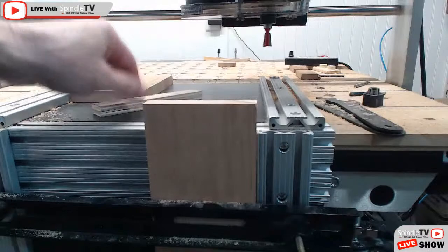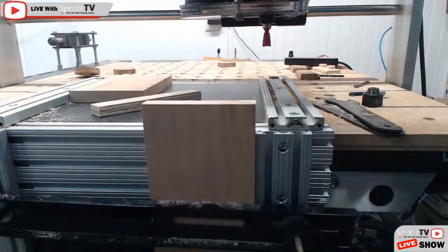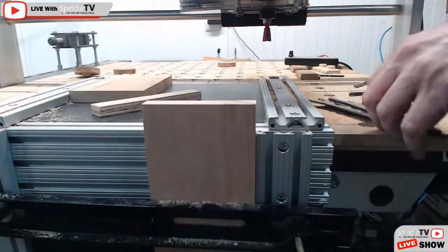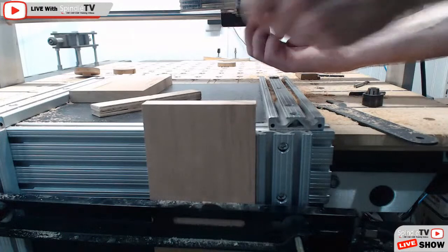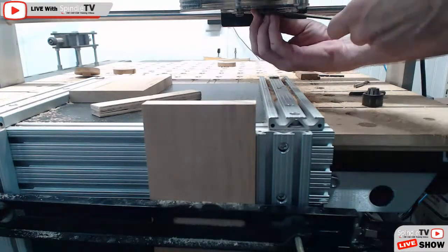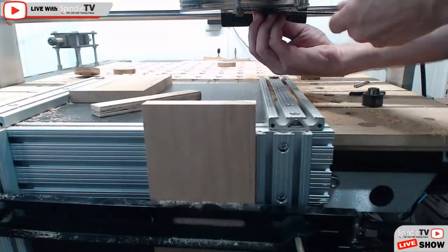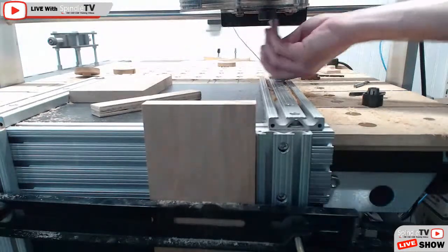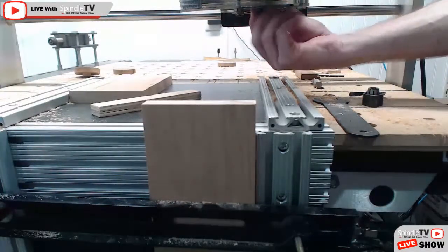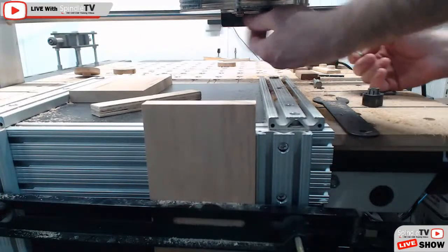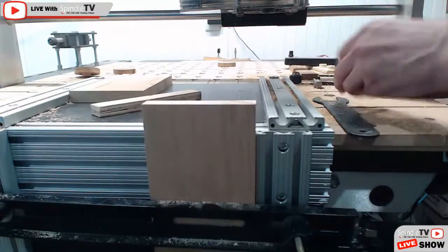All right. So with that in position, now I'm going to change back to the end mill bit. So bear with me a second while I do that. I don't like doing a lot of bit changes, so like I said, I would cut all of my end mill cuts first, flipping that board and doing both boards, the front and back tail board, and then do the dovetail cuts, and then I would switch to my pin board and do all of those cuts, which is basically no bit change on that. It's all end mill work.